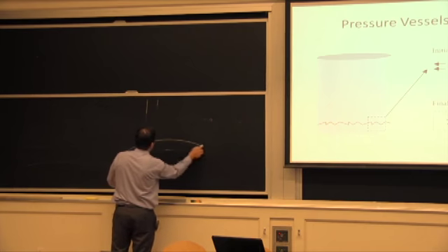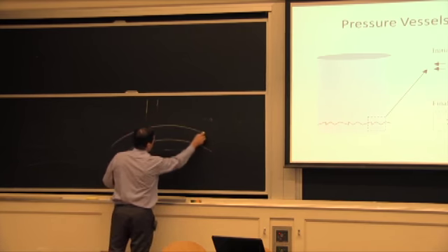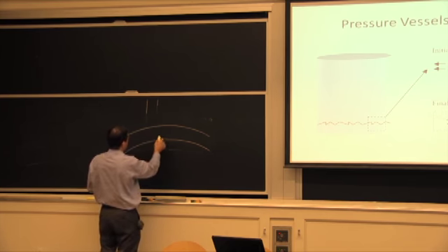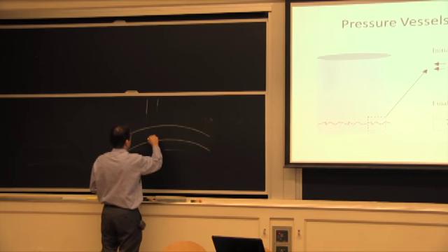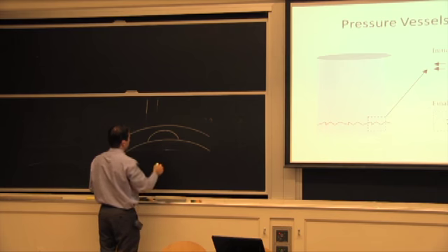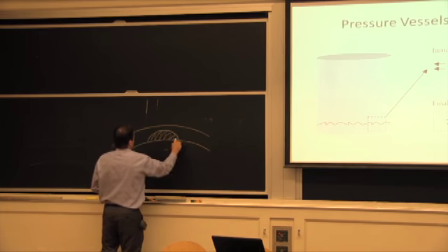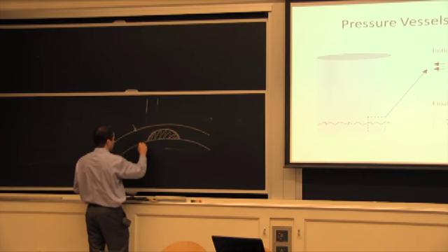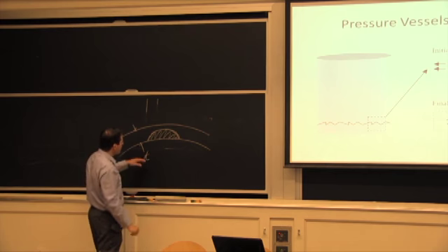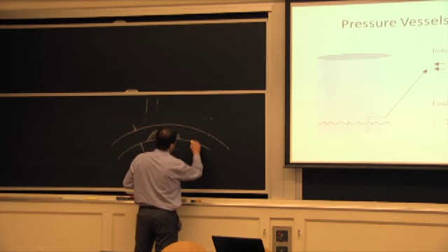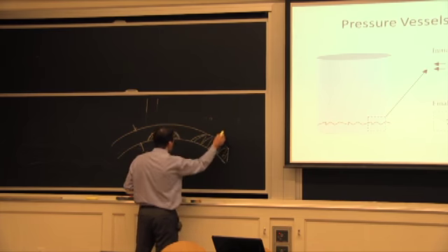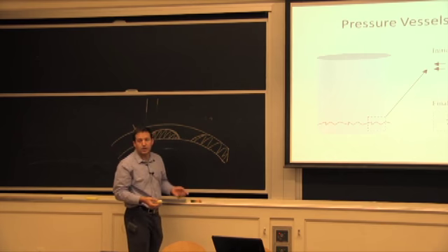So say we have a vessel, and we're looking at it from the top down. This would be a similar structure as this. We're looking down, and I'll say it's from the inside because of some chemicals. There's a crack that grew like this, a semi-elliptical crack. That creates this stress intensity at the front of the crack here. And what you want is, given your thickness, you require the material to be tough enough so the crack can actually grow all the way through, like this. Leak. And people react to it and fix it.